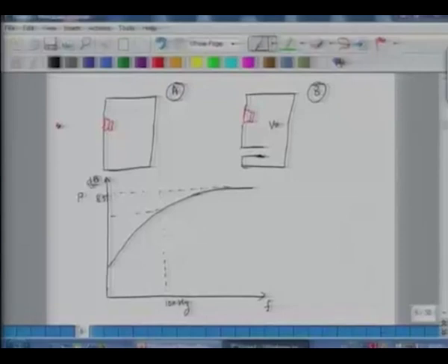if I want to improve the performance at 80 hertz. So when I do that, this transducer is producing SPL something similar to that, but my resonator is producing a heightened output at 80 hertz, wherever I am tuning it to be. So at 80 hertz, whatever is the tuning frequency, and in the neighborhood of that, I get a little bit of extra push. So I improve my bass performance.